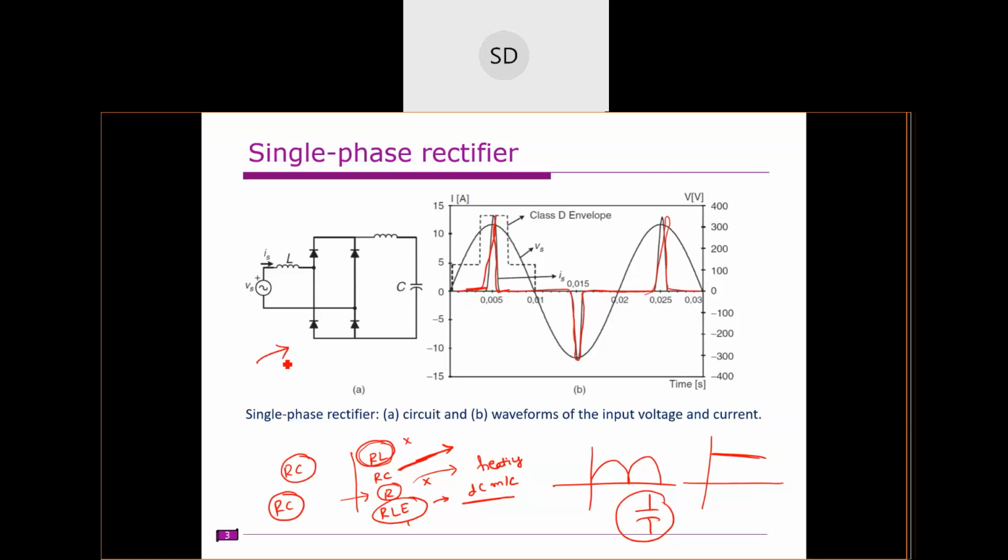This is the waveform particularly for battery chargers, right? For battery chargers, you normally require pure DC. To make this pure DC, they connect a capacitor across the output voltage. Therefore the current will be very high, which means the crest factor will be very high, right?